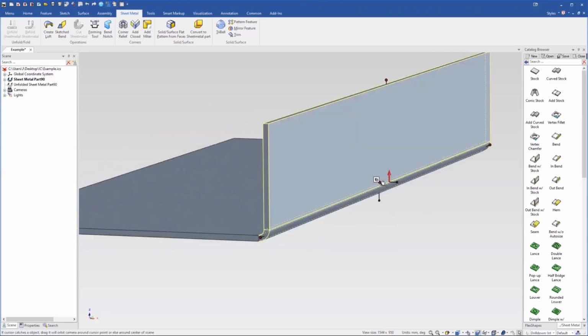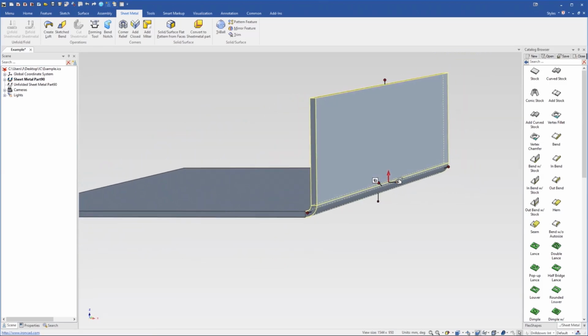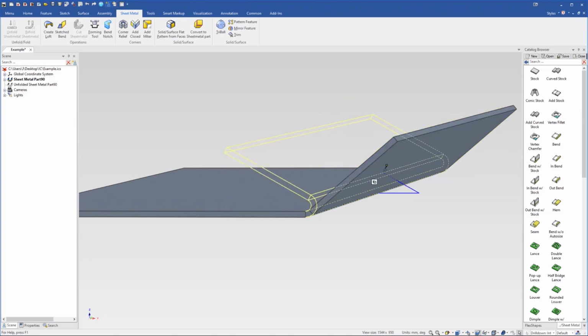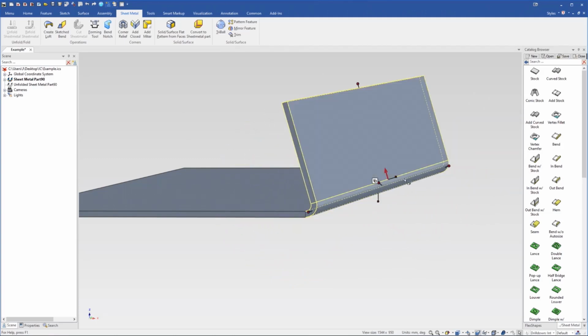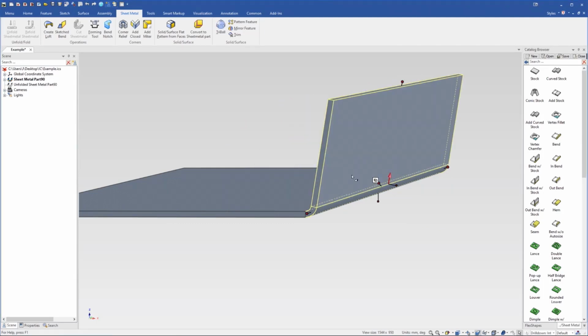You can also change the angle of the bend using these handles here. The handle on this side will change this side of the bend, the handle on this side will change this side. This can be push and pulled randomly depending on the angle you're looking for, or just to try out different angles, but it can also be precisely sized as well, just by right clicking and selecting edit angle, and then you can type in a specific angle. For example, we'll type 80 degrees, hit enter.